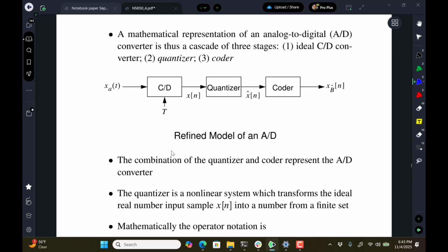The continuous to discrete is really just responsible for saying that the analog signal is a sample, and if the sample and hold is working properly, we have an analog sample that's a copy, at an instant of time, of the analog input. That's in the discrete time domain now, and now we have to quantize that.